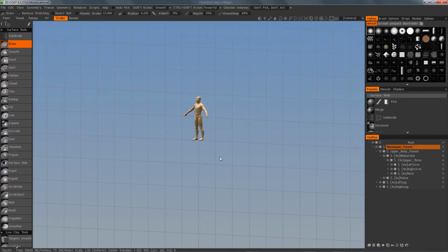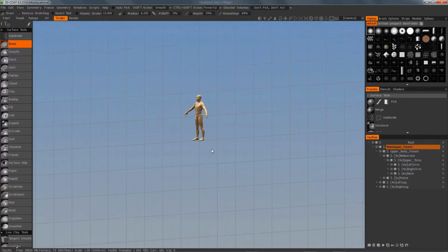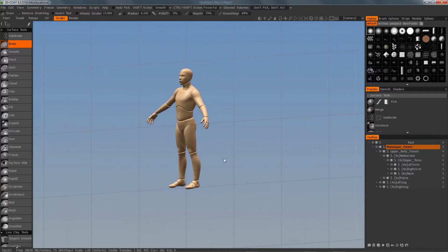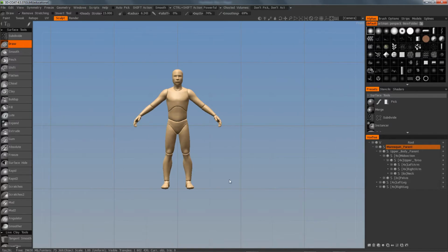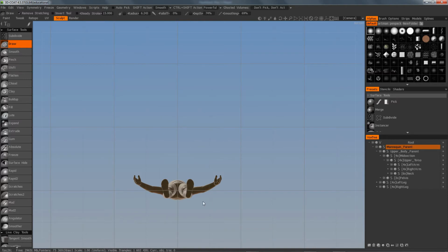It's also the way to get your best orthographic views. Remember, in Rhino orthographic views, top, front, side, well, the same thing happens here. But it's very elegant, actually. Instead of having a 4 viewport layout, basically you just revolve the model to roughly where you want it to be and then hold the Shift key down. And as it approaches where it's going to go, if you hold Shift, it will lock.